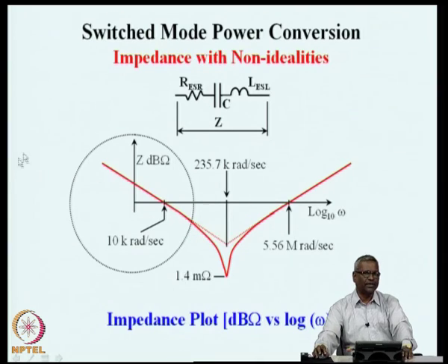At any other point, an ideal capacitor will have an impedance which is falling linearly all the way down, but you can see that the impedance of this, what we see here, and the ideal 100 microfarad capacitor are very nearly the same with respect to each other, only in this frequency range.